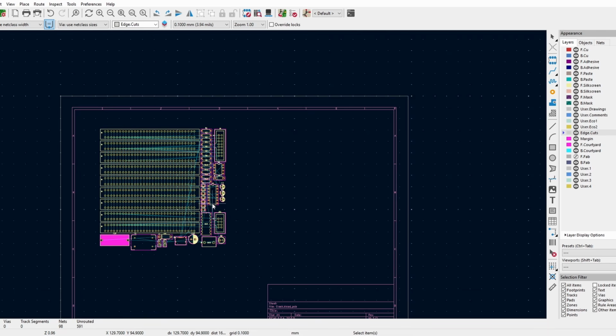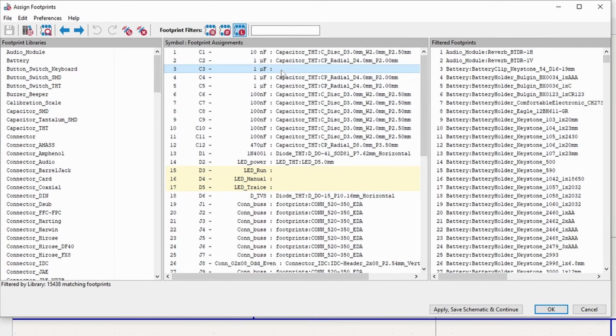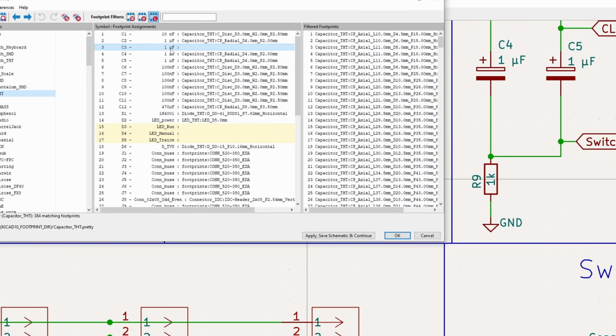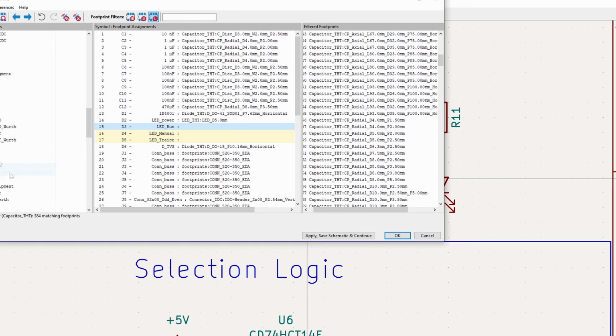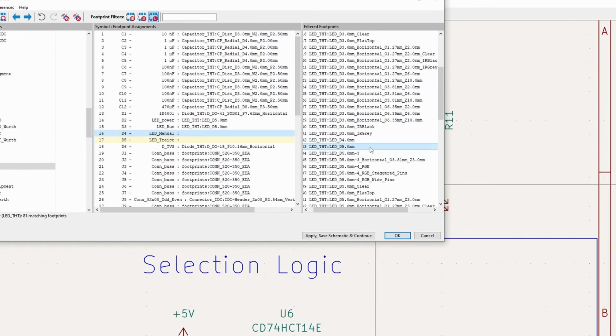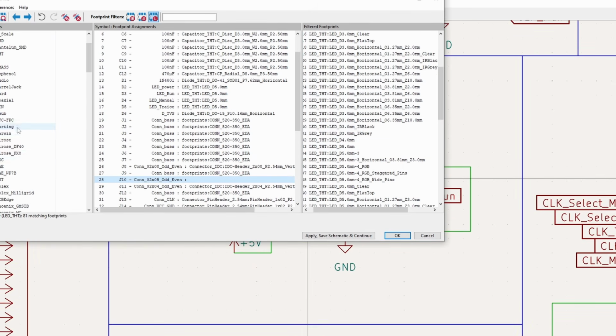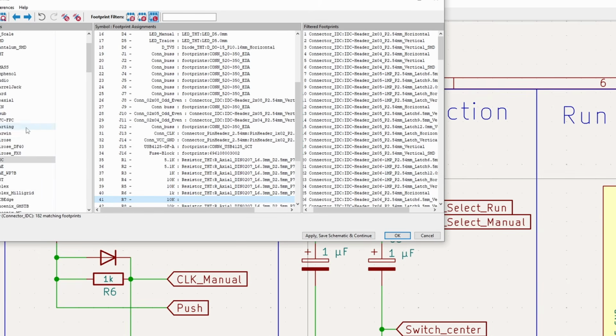At first I thought something had gone wrong though. Several of the components were still missing. After a fair amount of confusion, I eventually realized that those components simply didn't have footprints assigned to them yet. The schematic only describes the electrical circuits. The PCB editor needs to know what the physical part actually looks like in order to place it in the work area.